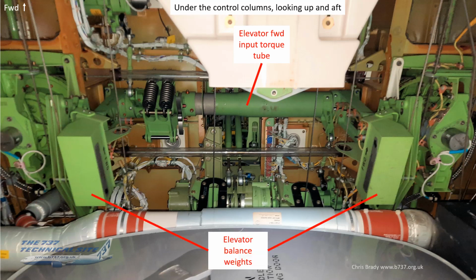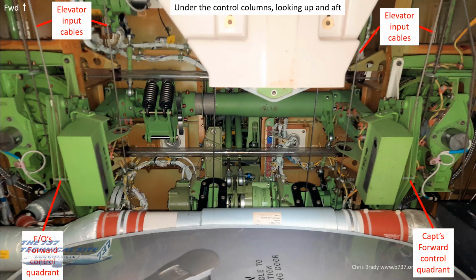Now, below that, you can see hanging down a pair of elevator balance weights. These are to counteract the weight of the control column, just to harmonize the input of the controls. You've got one on either side because, don't forget, in the event of a jam, you can override and move this input torque tube independently. That's why there's one of those on each side.